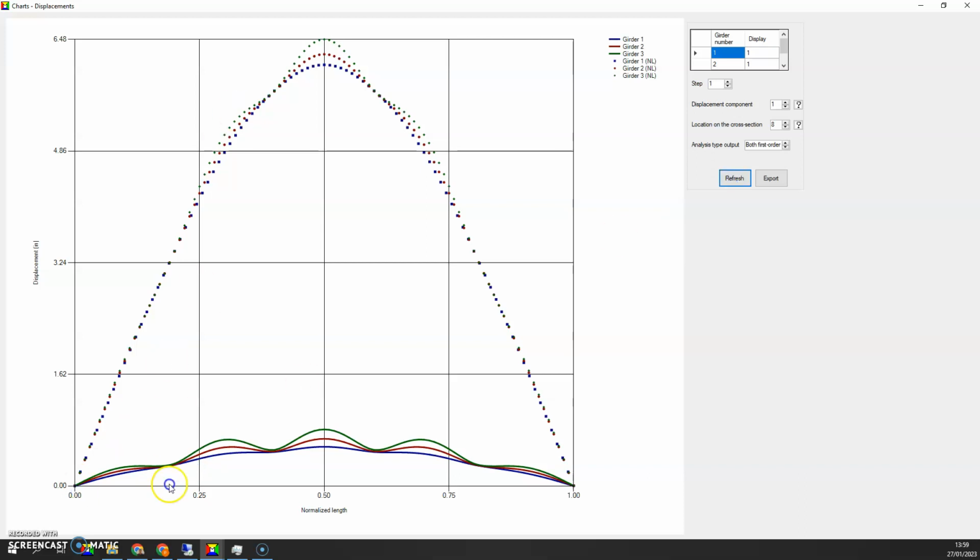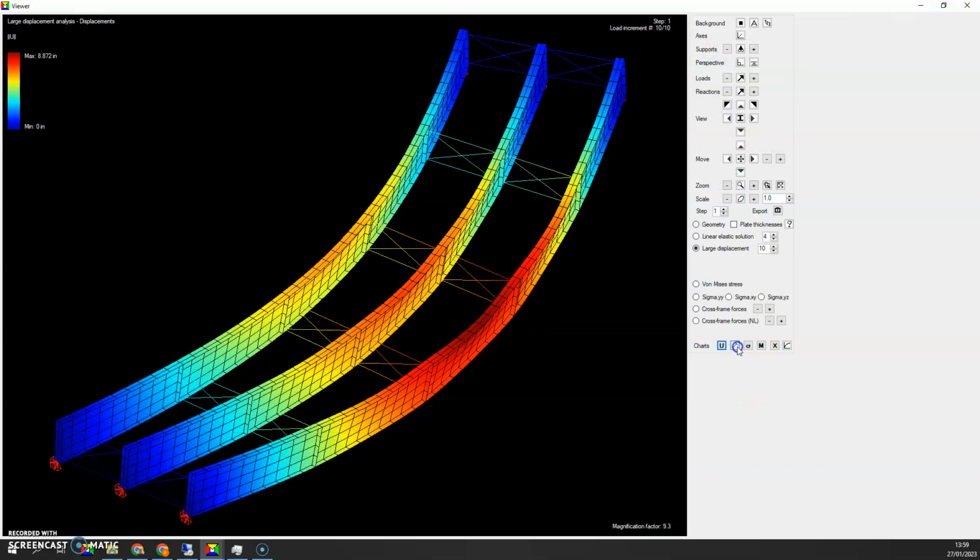We got something much higher. We can see that the lateral component of the displacement vector is about 8 times higher here. This is really the benefit of the second order analysis. We can really capture the out of plane displacements much better. So again, the large displacement analysis is about finding a state of equilibrium on the displaced shape, on the deflected shape of the structure.